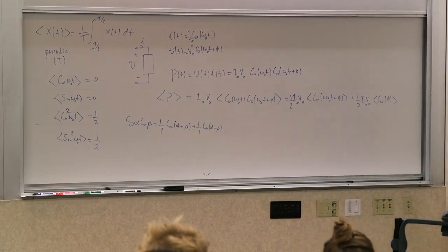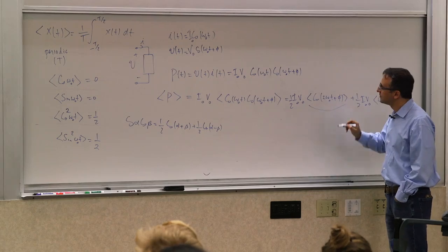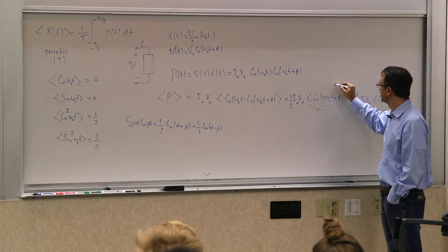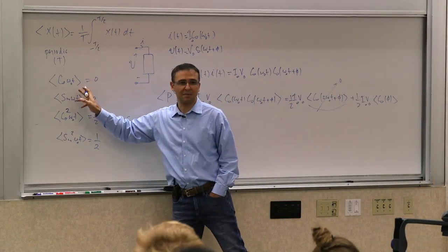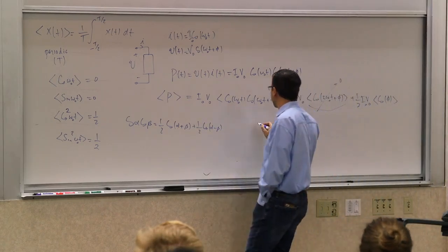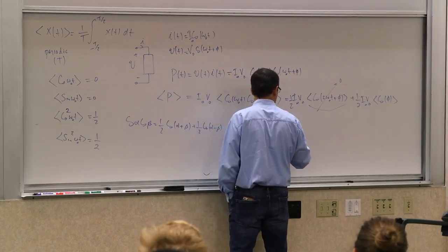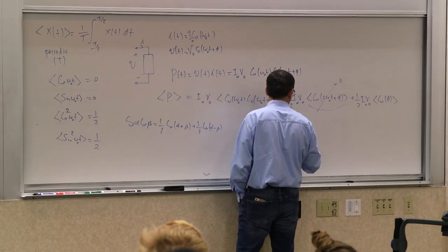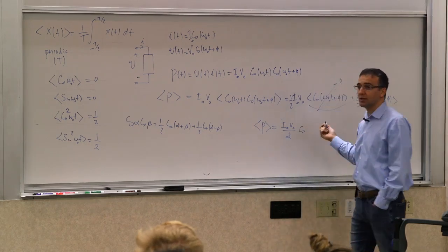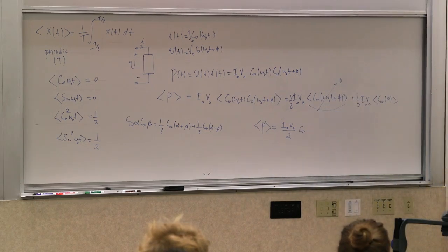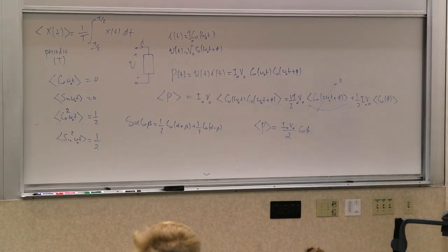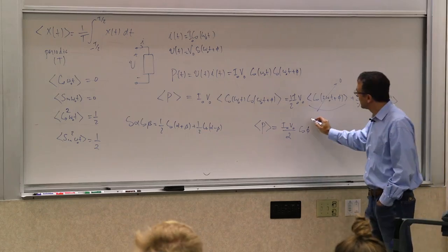Right? The difference. So what is this average? What is it? 0. By that, right? Doesn't matter if you add a phase to it. It's just shifting it. So what is left is that the average power is going to be 1/2 of the peak voltage and peak current product times cosine of phi. And what's the average of a constant? The constant itself, right? So it's cosine of phi. This is called the power factor.